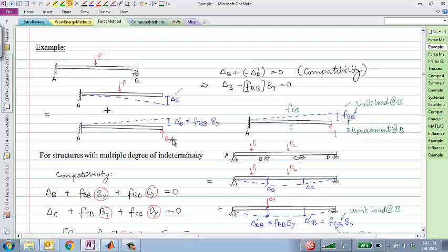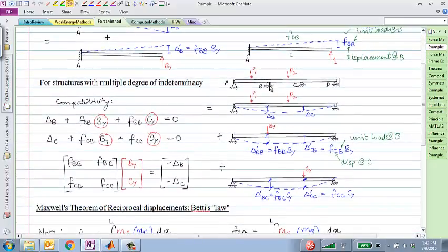We're going to use that force method to calculate redundant forces for our indeterminate truss. And I also pointed out that if you have multiple redundant forces, for example, two redundant forces, By and Cy, what you end up getting is a 2 cross 2 system of equations, right? In this, you need to solve an underlying determinate system at least 1, 2, 3, 4, 5 times.